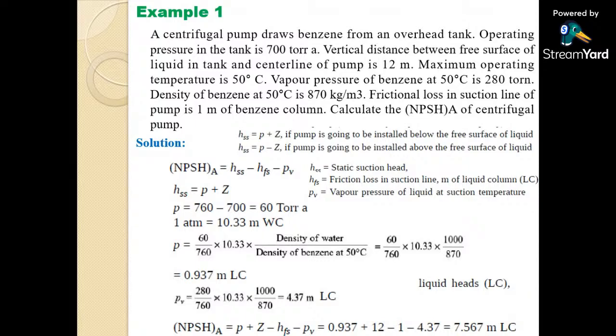Before calculating the pressure drop, we have to calculate the resistance in the pipeline. So frictional losses suggest the total resistance because of the viscosity and the structure of the pipe, that is, surface roughness. Okay. So HFS is already known to us. It is the head loss because of friction, and it can be calculated using the Darcy-Weisbach equation.